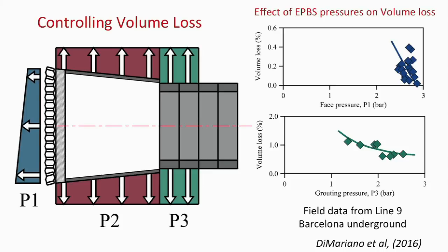is that these machines are designed for some pressures and for some working environment. And the experience is that if you increase those pressures, something begins to go wrong. For instance, I think there are some deformations inside. You cannot build your tunnel so easily, your dowels inside the protection of the shield, and there are internal difficulties to handle it. So you cannot increase this pressure for free.